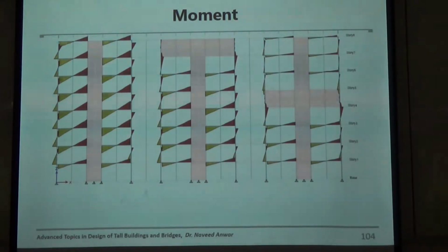So instead of putting many beams and putting a lot of reinforcement everywhere, we just put one big outrigger and reduced all the beams' reinforcement. This is very, very useful when you have a very tall building because you can reduce reinforcement in 30 stories by adding one outrigger, right? So there are many benefits to providing outriggers if we can manage it. But many times we cannot. So what do we do?